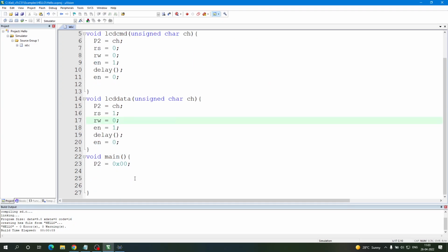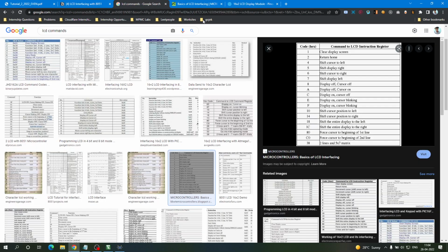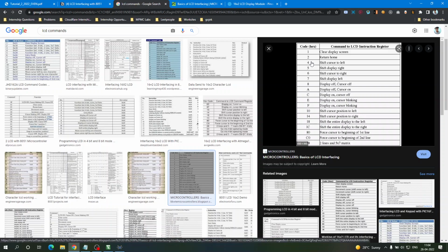because whenever we start sending data to the LCD display, we need to define some things. Initially we will be sending our first instruction, defining what type of display we will be using internally. We need to set that. Okay, so we have to use some commands. Here we can see, these are our commands